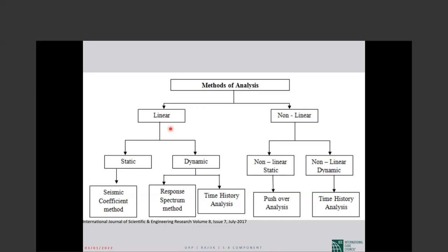For each of them, we accept some level of damage. What that means is that for each of them, we accept a level of increase with respect to the capacity. And this is defined by m values, which is equivalent to the R value, but is element-based.